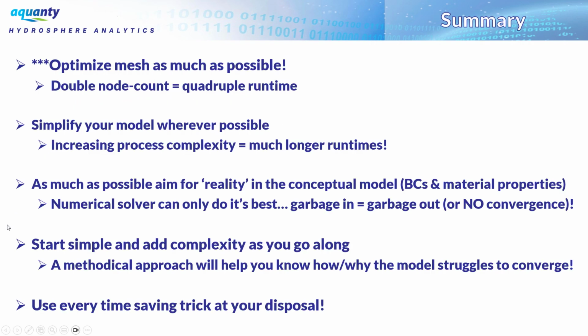Okay, in summary, optimize your mesh as much as you really can. This is really central, very important. Whenever you can, you also want to simplify the complexity of your model. Reduce process complexity, and that's going to effectively reduce the number of unknowns in the model matrix.